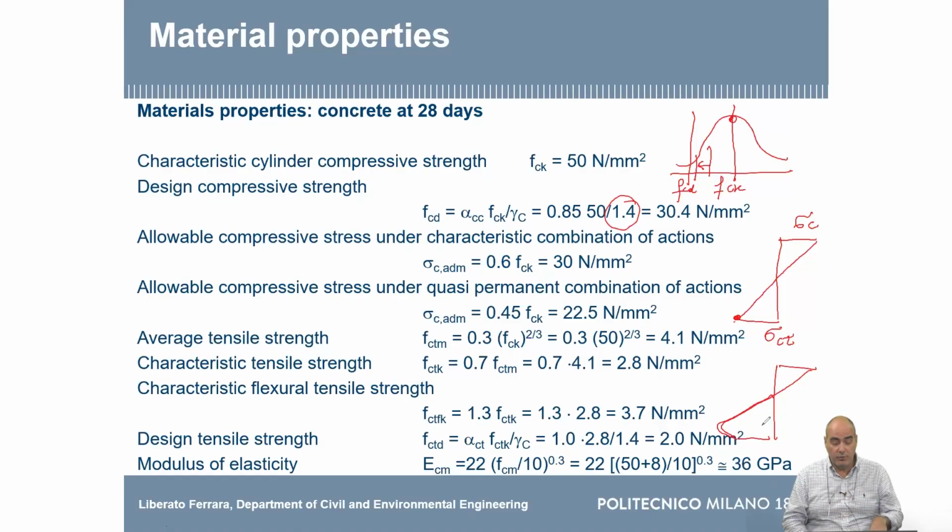And also we need to calculate the Young modulus of the material. Also, the Young modulus does not depend linearly on the compressive strength. The formula that we have here, once more, is a best fit. And it has been shown that this fits the data.